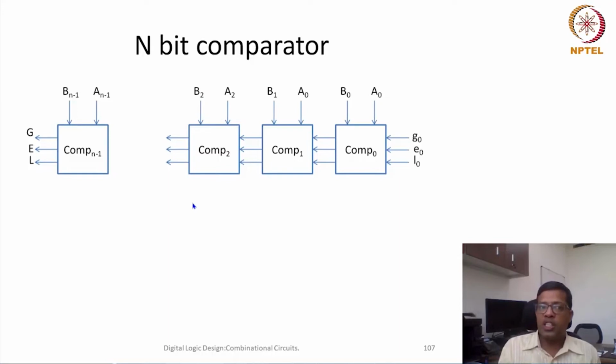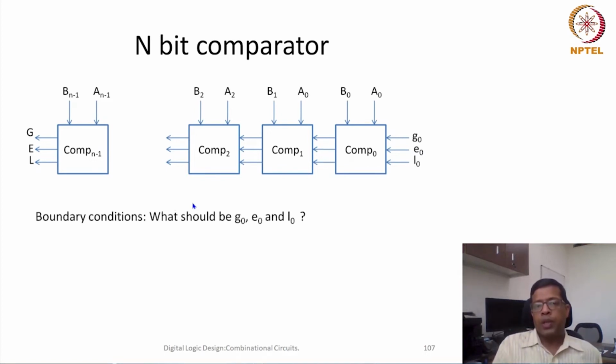In Verilog it is also easier, because we have the generate statement where we can simply generate from 0 to n, and then all these blocks would be instantiated. Similarly, if we design it for a layout, iterative designs are easier for placement, because you can wire them easily and the interconnection is very less.